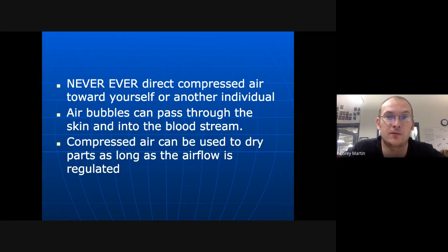We're talking about 150 to 170 pounds of air at the regulator. So you always be very, very careful when using compressed air. And you never direct it toward yourself or anybody else with a blowgun or a blow nozzle. There are certain situations where we might use compressed air to clean off a workbench or dry off a part that we have cleaned in the parts washer. And in that circumstance, we're going to make sure we're using very, very regulated air pressure down to about 25 or 30 PSI.